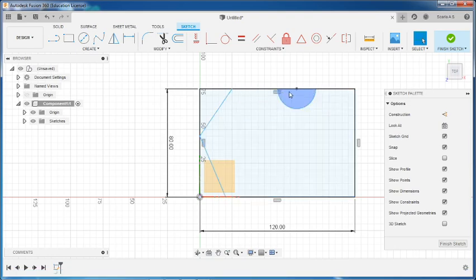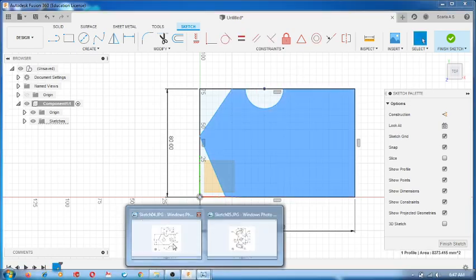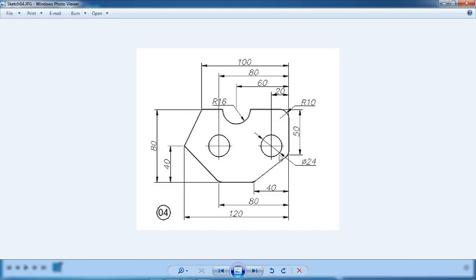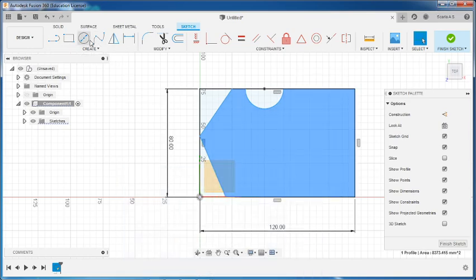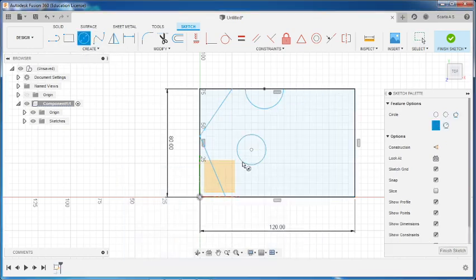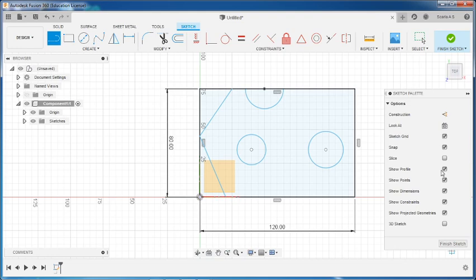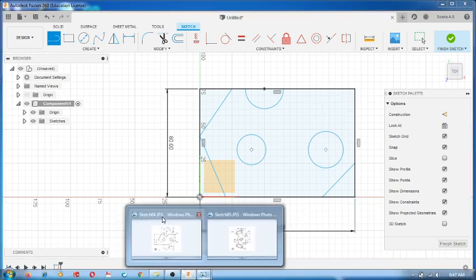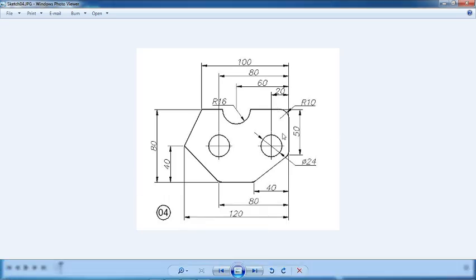Drag. You can select and drag this. So just move somewhere here. Then here two more circles and two more lines, that also we will make. Press L, draw one line here. Okay, that's it. So we will give the dimensions one by one.